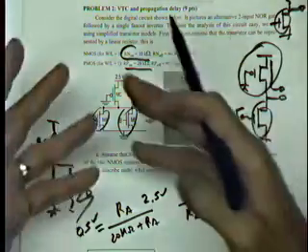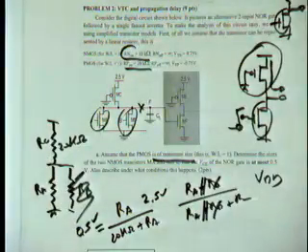So it's just realizing that this is a resistor divider. You have a certain output voltage. What is the worst case condition? Fill in the equations, and you find the size of the transistor.